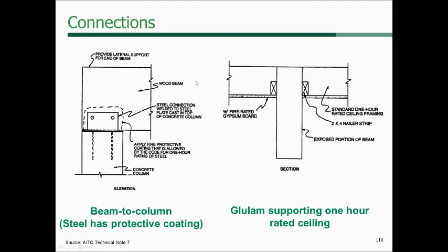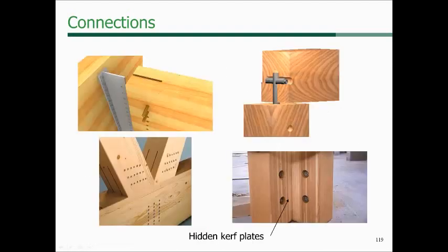Here's another application where we have a steel connection, and the wood beam is bearing on, in this example, a concrete column, and a steel connection, protected by an approved fire protective coating on these side plates, and a sealing application there. These happen to be actual proprietary connections.